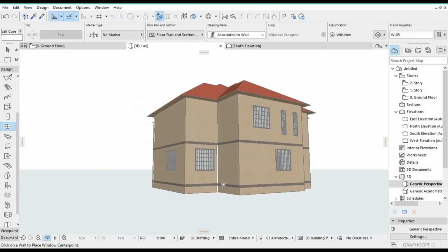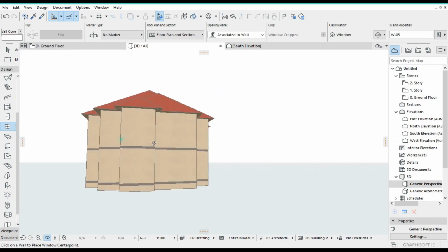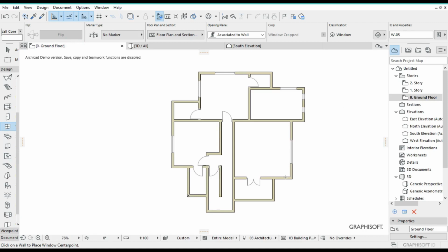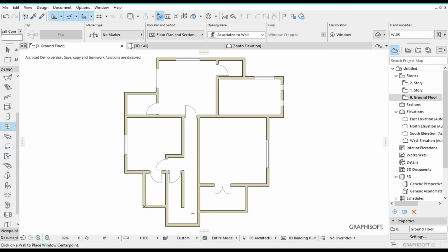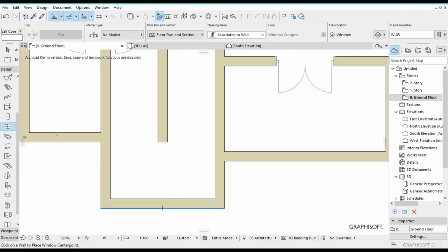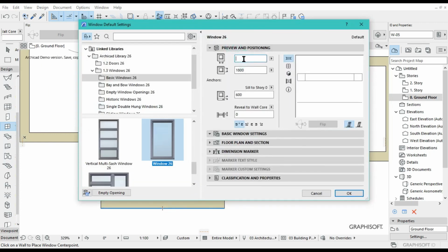The other thing we need to do is add the window for the staircase part, the stairwell. For this one I'm actually going to add 2 different windows. There is one, Control T, 2000 millimeters wide, 1350 millimeters high, projecting at 1500.